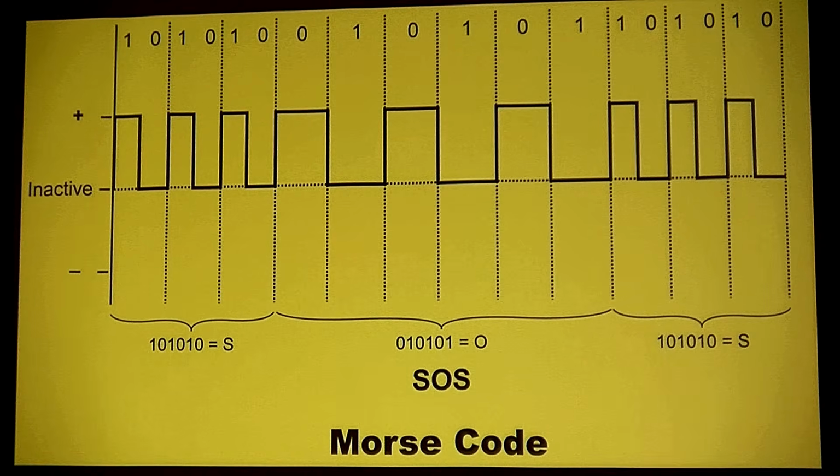I'm going to have breaks or divisions. So here what we see is we've got these divisions. Now I want you to notice that every bit, that's a bit, that's a bit, that's a bit, that's a bit, that's a bit. Do you see how every single one of these has a rise and a falling edge? This is very easy to keep track of when I have different clocks in different modules. The more transitions that I have, the more edges that I have to change, every time I have an edge, I resynchronize the entire bus. If I have a falling or a rising edge, every module syncs to that edge. Does that make sense? Every module.